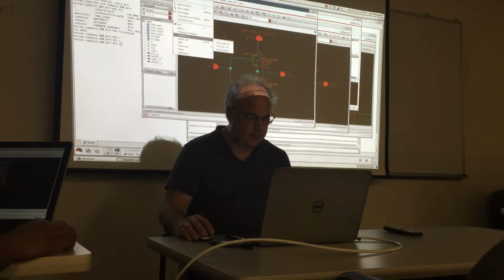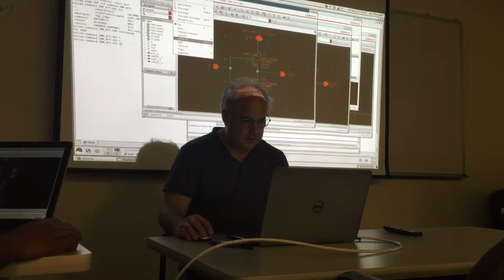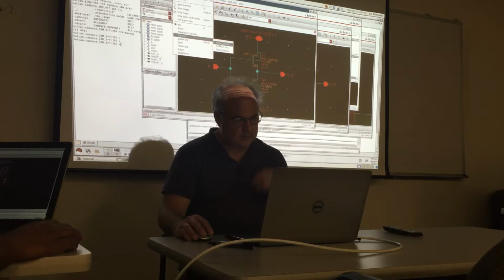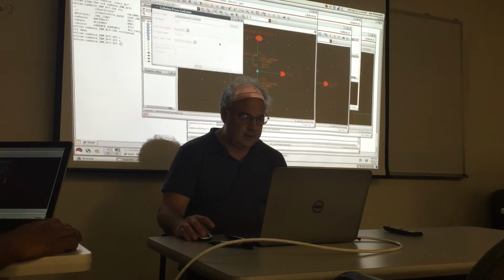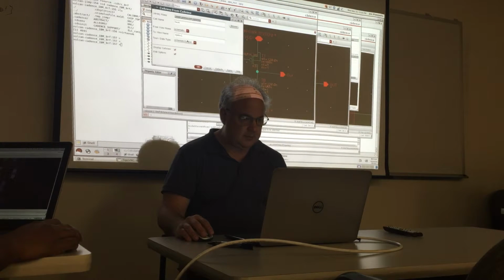It is under create. It's under cell view create, from cell view. Yeah, create cell view from cell view. Oops. Okay, don't forget where this is, or you'll look around for half an hour before you find it. Create cell view from cell view. Hit OK, and then it'll give the from name schematic to name symbol.